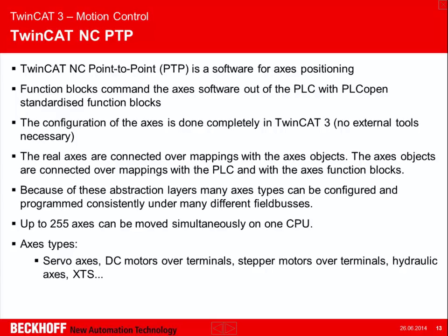We support different axis types, so of course servo axes, but also DC motors connected via different terminals, stepper motors with terminals, hydraulic axes, and also the XTS is supported with the same function blocks.